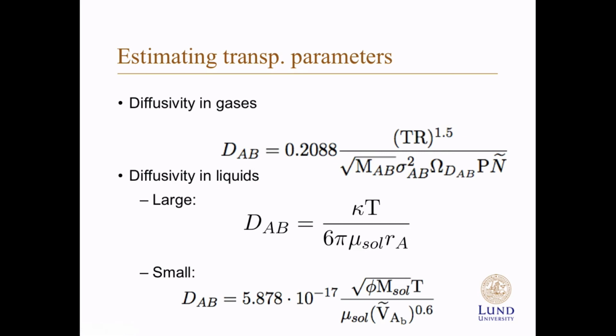So if you get an example where you need to use these things for liquids, note that the viscosity of the solution might be tricky, but if you have low concentrations, you can, in our course, simplify and say that the viscosity of the solution is the same as the viscosity of the solvent. But to get full points, you should better write that in your solution, that I now assume that I have the same viscosity in the solution as I have in the solvent. And if you have a small molecule, you use Wilke-Chang's equation instead here.